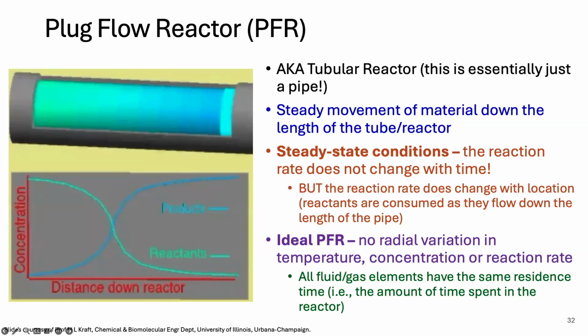A key feature of PFRs is that they operate under steady state conditions, meaning the reaction rate does not change with time. However, the reaction rate is going to change with position, since our reactants are consumed as they flow down the length of the pipe. So the longer they spend in the pipe, i.e. the longer the reactor is, the greater the reaction will be overall.